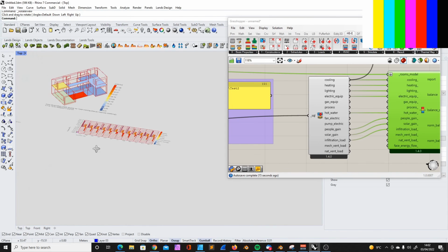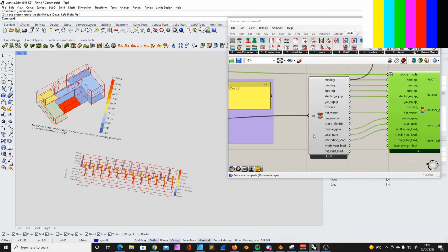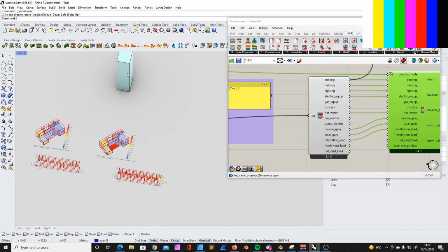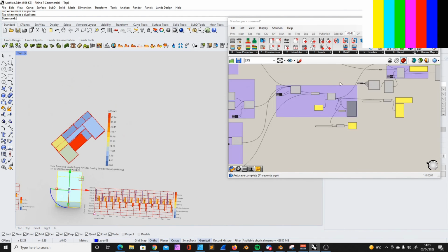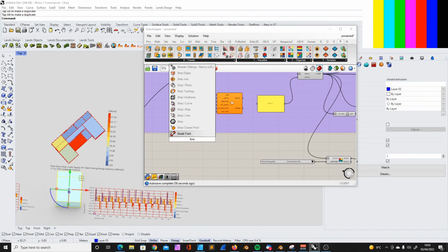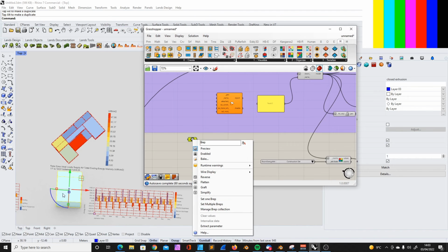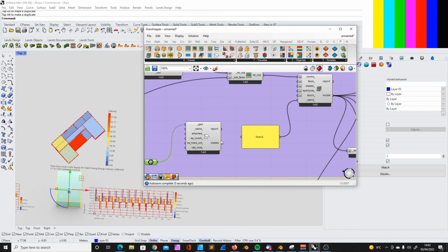And I also want to show you that a building, for example, can have an influence on this output now, because we have the solar gain. So we can set, for example, a building as a shade object. Let's do that. So we can look at how that influences our model. And we need to set this here. So let's get Honeybee shade object. The BWrap container. Can set one object. This is this object here. And we put this in here and put this into shades, and it will rerun automatically.